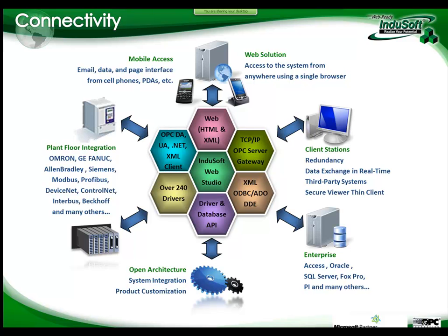We offered OPC DA, spec 2.05, since always, and now with version 7, we added OPC Unified Architecture, or OPC UA, and OPC .NET. And later on, we added XML connectivity and support too. So our OPC solution is very complete. Even for Windows CE, you have OPC DA, and you have OPC UA as well now on version 7.1.